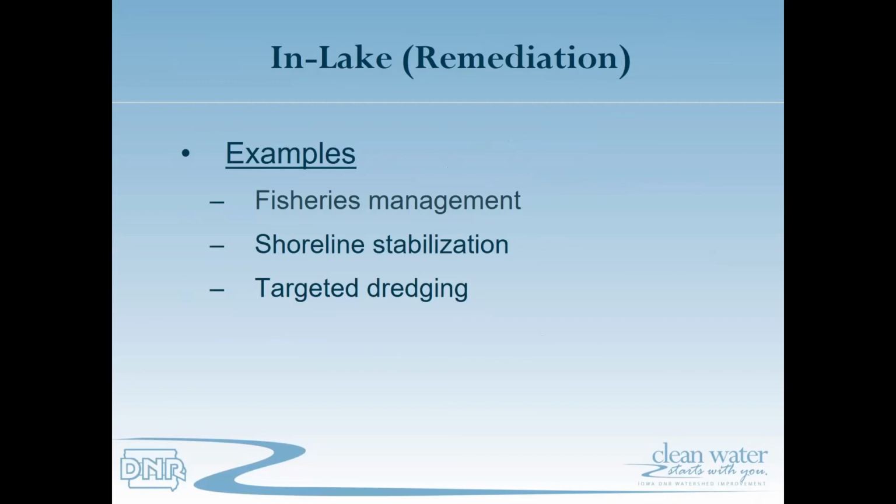Shoreline stabilization, so that can be adding riprap or jetties or things like that to the actual lake perimeter to slow down wave action from eroding soil. And then also targeted dredging. So that's actually going in there with mechanical processes to remove soil, remove phosphorus from the bottom of the lake. And the document describes some of those renovations that took place about 8 years ago, and how much money was spent and what they all did. And we can see from the slight improving trend of the water quality that they may have some benefit.